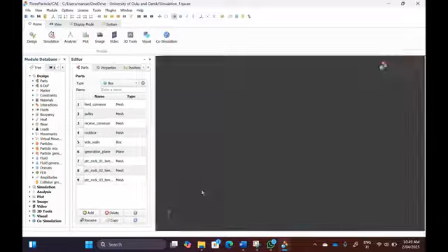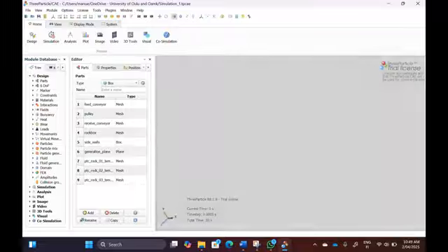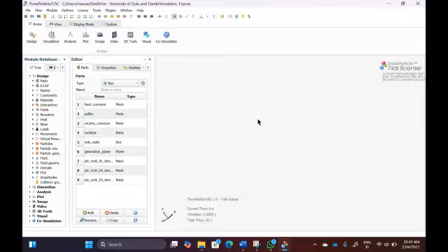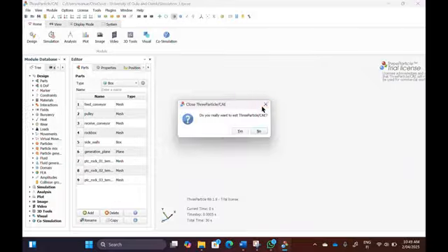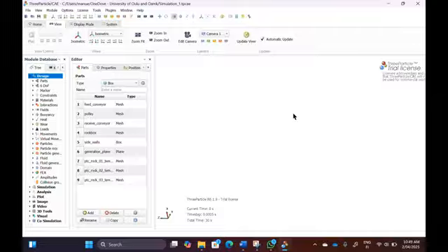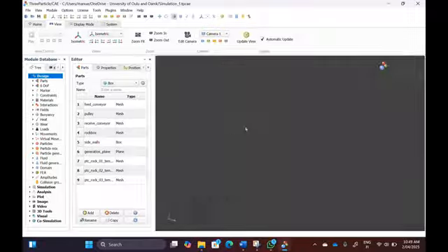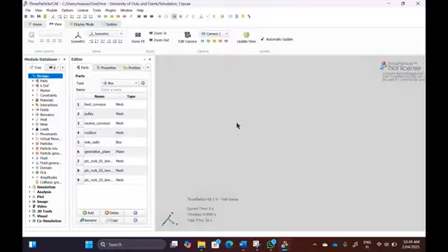Import keyword file. And there it is. Double click it. Now simulate, the simulation starts. Yes, right here. Save it first. Choose your tests or whatever. Yeah, looks good. Save. Start simulation. And after that, the particles should start.